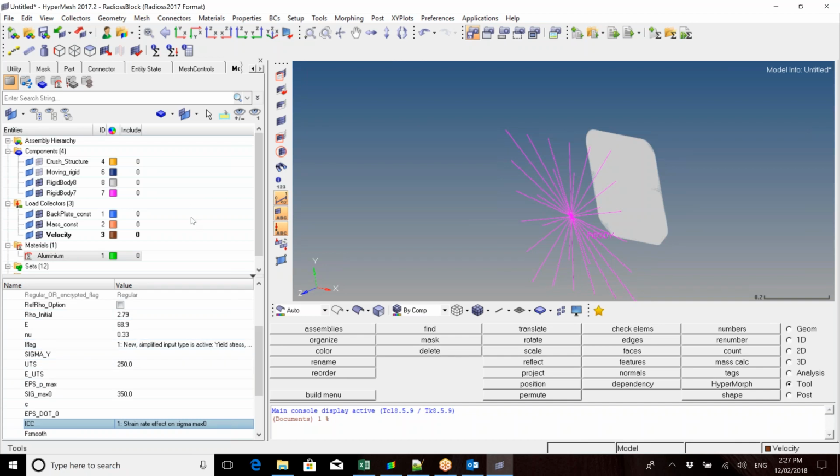so with the other materials as well. This is your basic M2 elastic plastic. Just some other basic material laws that you have. If you look at law 27, that is a plastic brittle material law. I'm fairly sure that would be used a lot for plastics. Plastic materials that are really rigid and quite brittle, they'll snap and they won't have a large plastic region. Law 28 is your honeycomb law. You've got law 14, which is a composite solid. So if you are using composite structures, law 14, and then law 25 is a composite shell. So making sure you understand the difference between those.